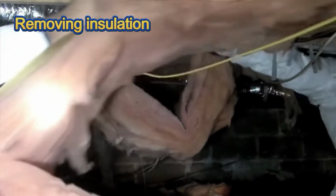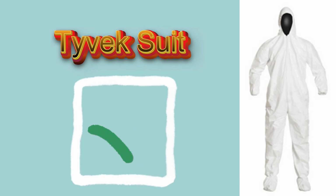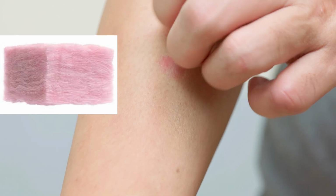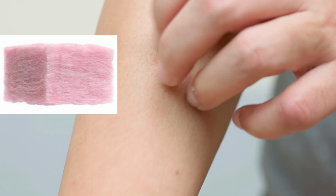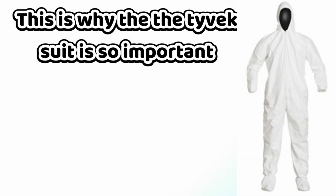Removing any batted insulation currently installed in the crawl space. It's an excellent idea to wear a Tyvek type of crawl suit when doing this. This fiberglass type of insulation is very uncomfortable to work with. After doing these jobs, you can feel very itchy and may feel as though someone has cut your skin lightly and repeatedly with a knife. I use that description because it's the best way to describe how uncomfortable it can be to have any of your skin exposed to the insulation when completing this part of the job.